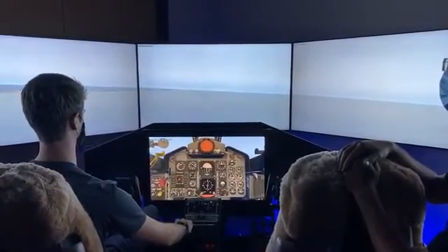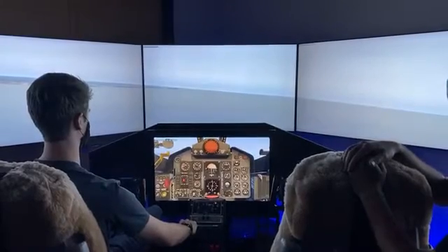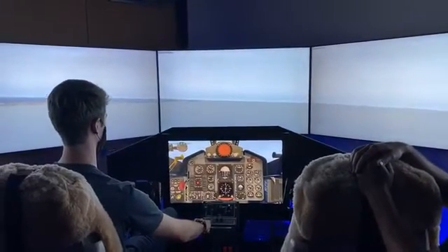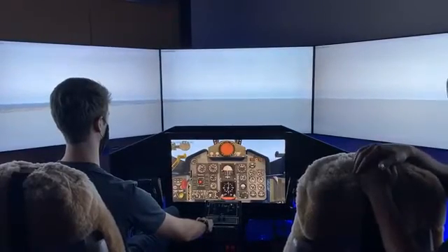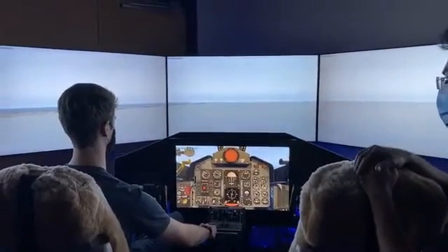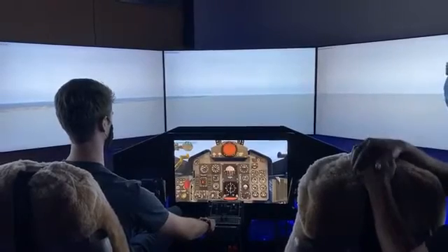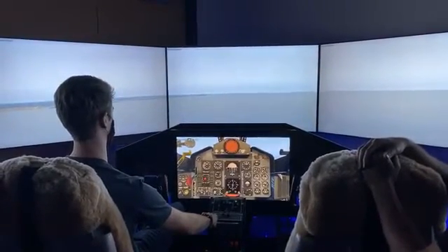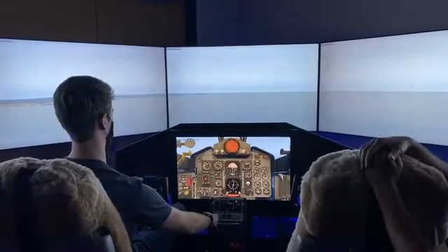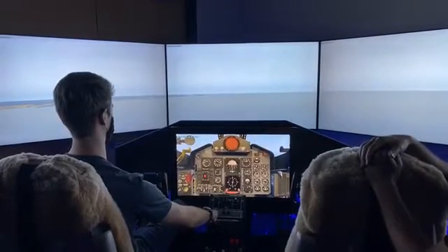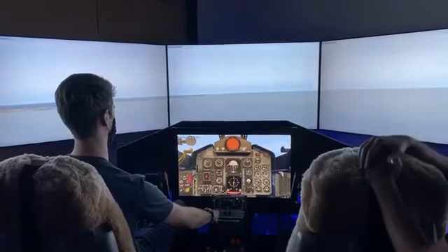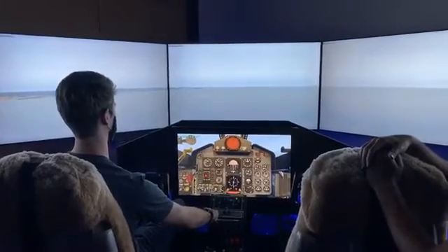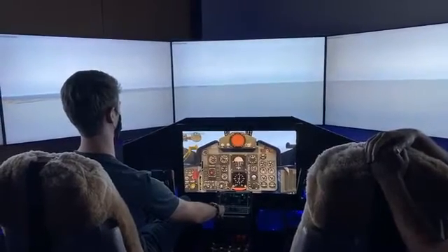The system helps guide the pilot towards the aircraft carrier, as you can hear. It's kind of hard to see, but that phrase they said at the beginning, when they said call the ball, it's a phrase they use in naval aviation, which tells the pilot to start looking for a set of lights on the left side of the runway of an aircraft carrier. And that tells them how high or low they are and if they're over their speed or not.